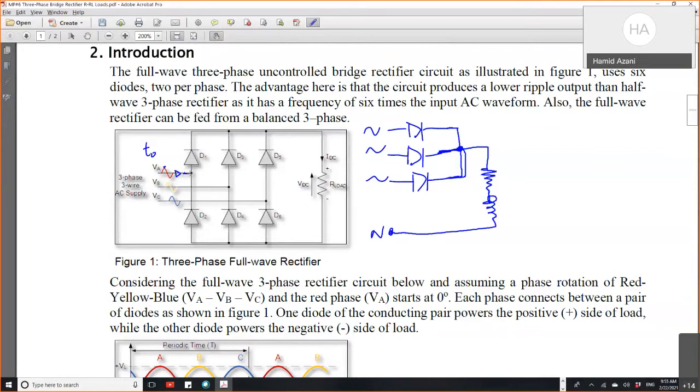So this current will flow through the first diode. Okay, it has two paths, this one and the one at the bottom here. The bottom one has a cathode here, so it's blocked. This diode will block the circulation here. So the current will have only this direction to follow, and here also it has another intersection. So here also you will find this D3 and D5 blocked. It will continue toward this and it will generate this voltage across that resistor or this load.